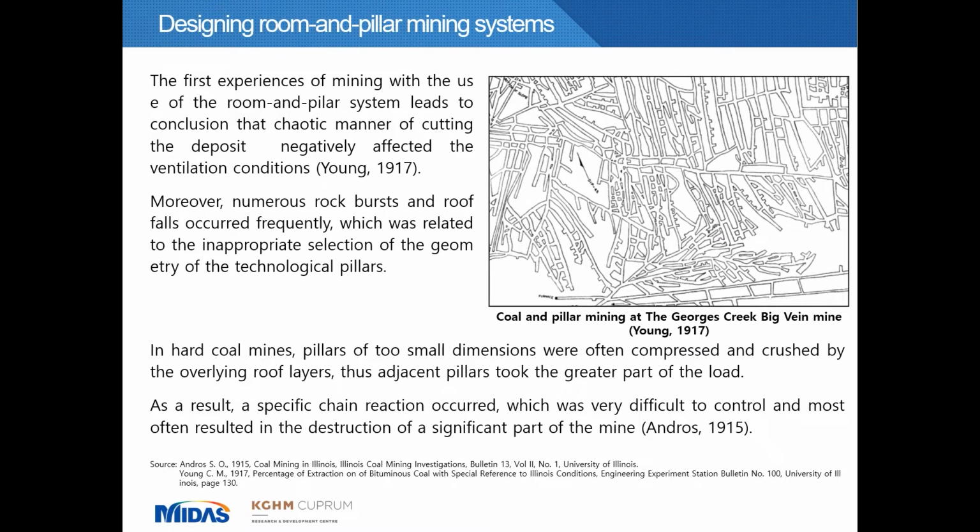In order to bring you closer to the challenges related to the design of room and pillar mining systems, a few words of introduction in the field of the development of this kind of exploitation method. The room and pillar mining system is one of the oldest methods of underground mining, mostly of deposits located in the hard rocks. Initially, the exploitation was carried out in a non-systematic manner. I mean that the size of the pillars was selected empirically, and for example, the access ramps and the sidewalks were laid in the most convenient way.